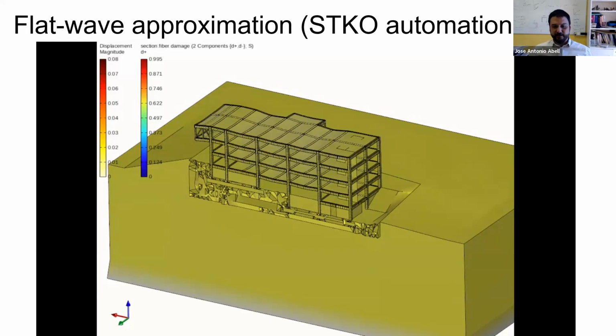But it's limited in the sense that if you're going to very large models, you need to first load the whole model in your rank 0 processor, and then you need a lot of memory for that, and then it gets distributed. There are also limitations because that distribution phase requires that all the elements and all the materials that you're using implement some specific member functions to handle the transfer. So if you're using some component that does not have that part implemented, it's not going to work.